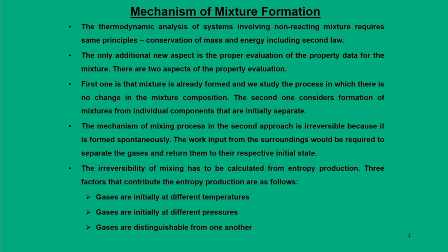Composition also changes. So these two situations we are going to model. Now when you deal with the second aspect, the mechanism of the mixing process, this mixing process is always irreversible, because the mixture is formed spontaneously. If you want to separate the gases out of this mixture, we would require work input from the surroundings, and this is never possible. So we call this process an irreversible process.